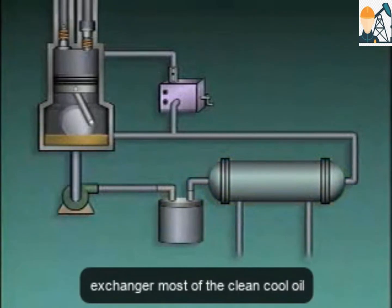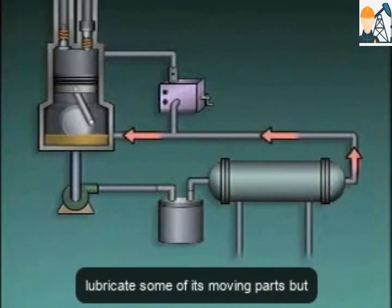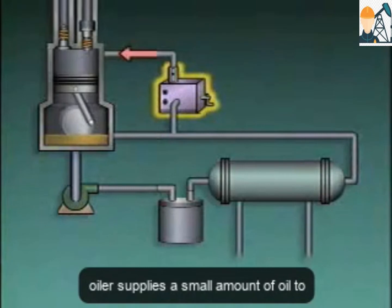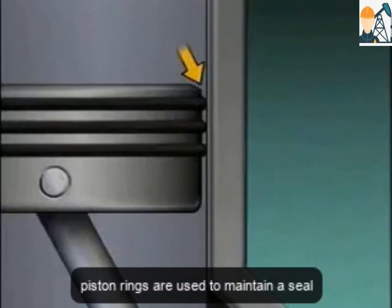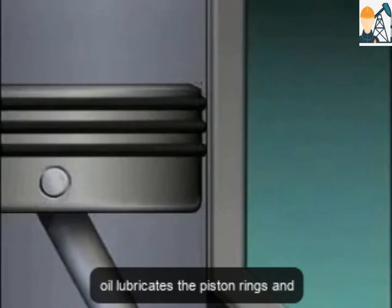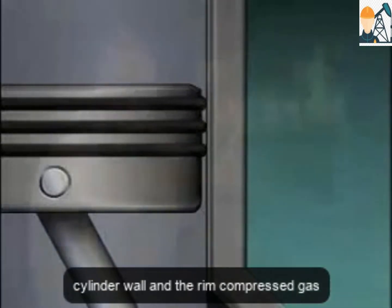From the heat exchanger, most of the clean, cool oil flows directly back to the compressor to lubricate some of its moving parts. But some of the oil flows to the oiler. The oiler supplies a small amount of oil to the compressor cylinder. In the cylinder, piston rings are used to maintain a seal between the piston and the cylinder. The oil lubricates the piston rings and helps seal the space between the cylinder wall and the ring.